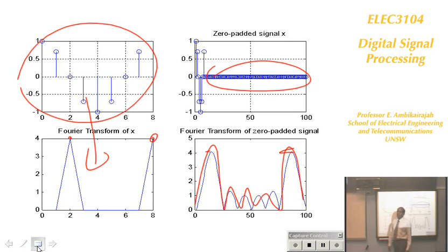So, summary: FFT is the way to go, and make sure your number of samples is a power of 2, then the fast Fourier transform can be applied. And if you don't have a power of 2, in MATLAB it will add extra zeros to make it a power of 2 so that it can run faster. So the discrete Fourier transform basically gives you frequencies at discrete frequency positions, called K, which are multiples of the resolution.